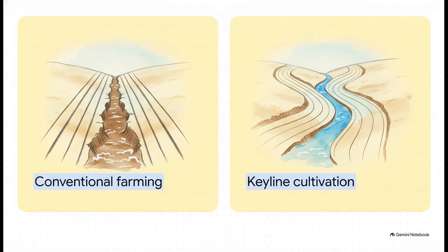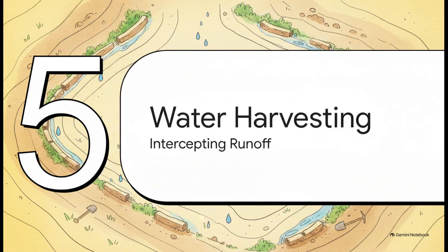So unlike standard farming, which usually just runs parallel to a fence line and accidentally creates trenches that speed up erosion, keyline cultivation uses precise off-contour furrows. These furrows literally comb water out of saturated valleys and spread it evenly onto the dry ridges. You're creating subsoil channels that intentionally defy the valley's natural drainage, ensuring the entire slope gets a nice, even drink of water.